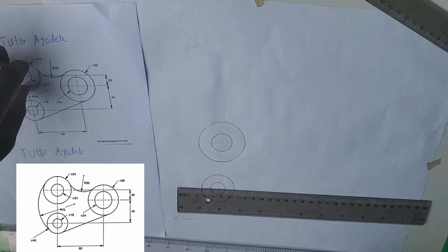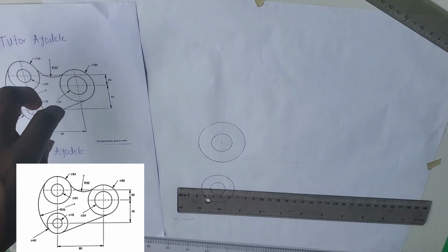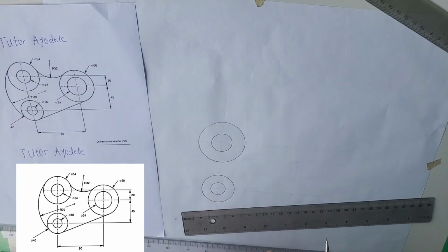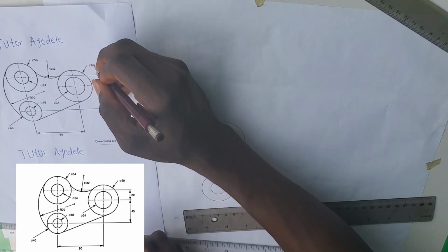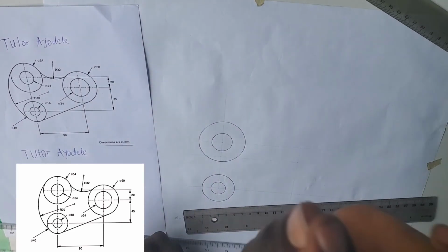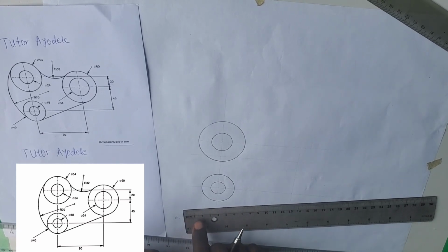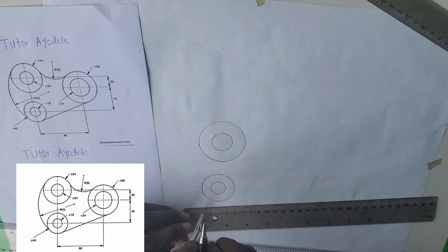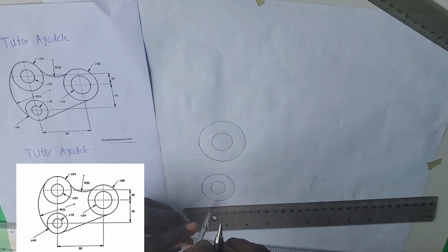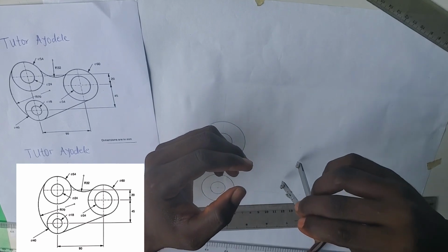Now this is the other circle. I want us to draw this third circle before we connect the lines and do the tangency for the lines. This other circle, the midpoint is at this point that we marked, this point here. The outer circle is diameter 60 millimeters, so in radius it is 30 millimeters. 60 divided by 2 is 30, and that will be 3 centimeters on your meter rule, because it is calibrated in centimeters. Let's measure it from 0 to 3. All right, this is it. From this point, draw a circle as big as that.